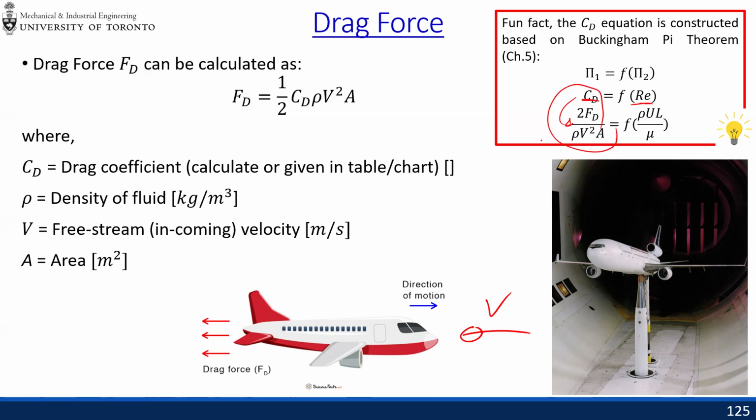So we rearranged it to come back to a form that gives us a drag force rather than the drag coefficient. Now, the right-hand side is a function of Reynolds number, which is why that also contributes to it. When your Reynolds number increases and changes the flow regime, your drag coefficient quite often also changes.